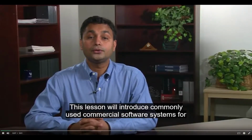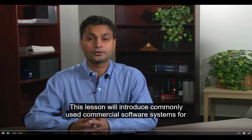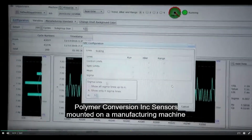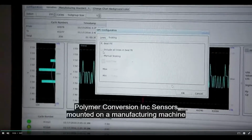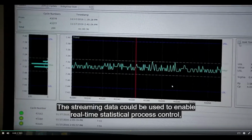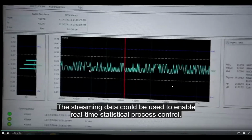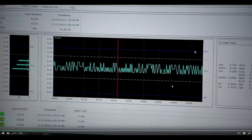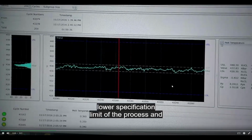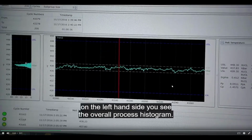This lesson will introduce commonly used commercial software systems for manufacturing process control. As you see now, at a local company in Western New York, Polymer Conversion Inc., sensors mounted on a manufacturing machine are providing real-time manufacturing process data. The streaming data could be used to enable real-time statistical process control, or SPC. On this displayed chart, you can see in blue lines the upper and lower specification limits of the process, and on the left-hand side, you see the overall process histogram.